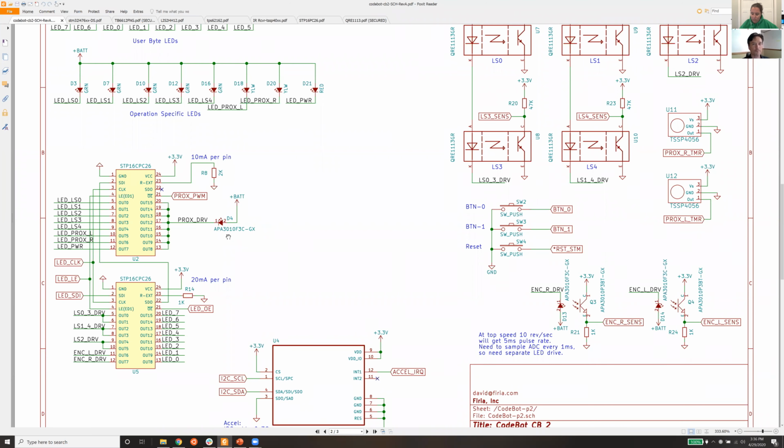If you use BotCore, we prevent you from setting it. But if you're directly manipulating these, there's one little warning. I think this is the one thing that you could probably break if you tried hard. You'd have to replace this LED if you did, which would be to turn all these on and leave them on. Then you're not pulsing this one, you're setting it to a continuous current that's higher than it's rated to handle. It might survive it, but it's not recommended. So take a look at that before you play with the prox driver. Everything else, though, play with to your heart's content.